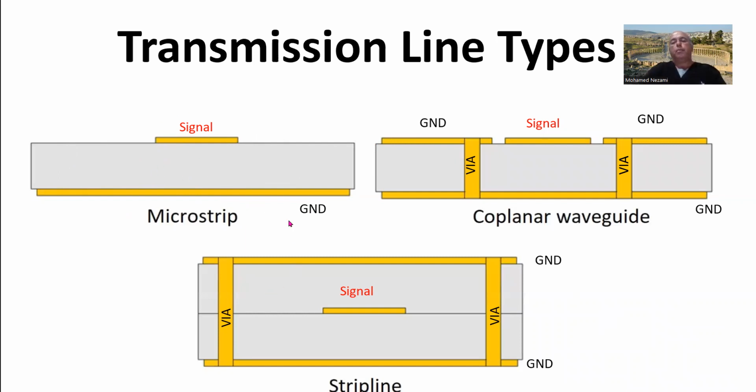It's pretty common, and many of you have used it, of course. The other one is a coplanar waveguide, and that's nothing but the same as this here, except it's bounded by two ground strips on top. These could be copper core, or they could be strips of copper that go along what would at one time be the microstrip line. In this case, it's a coplanar waveguide, or a grounded coplanar, because there's grounds.